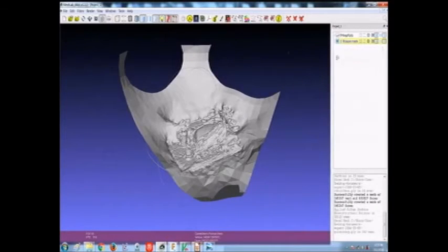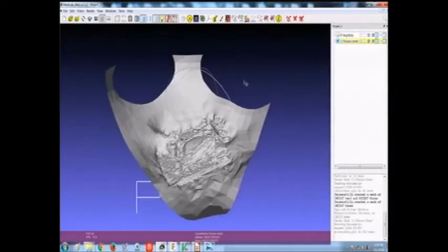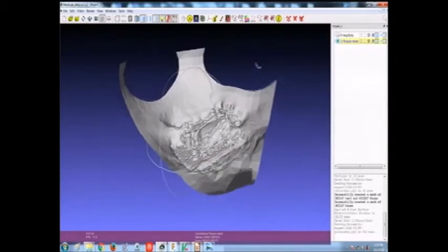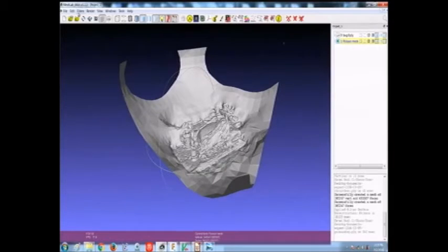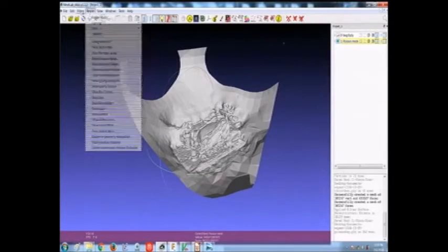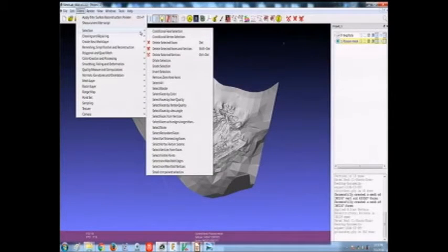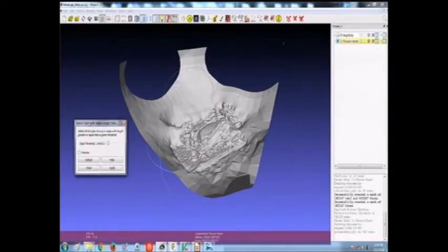So we'll be dealing with this Poisson mesh, right? We got a bunch of little outliers and a bunch of extra little surfaces that we don't need. We want to delete all these extra, mostly artificial surfaces out here. So in the filter menu, we can select edges based on their length right here, edges longer than. And the default edge threshold is at about the 50th percentile mark.